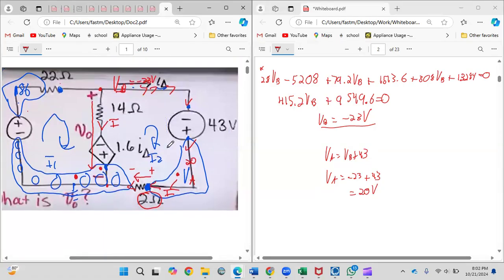So you just do nodal analysis. Same steps. You label your reference. You label your nodes. Label the nodes you know the voltage for. Look for your supernodes. Loop them together. Do the equation for the supernode and any other unknown nodes that you don't know the voltage for. And after that, you do your analysis technique: the node you're coming from minus where you're going to, divided by the resistor in between.